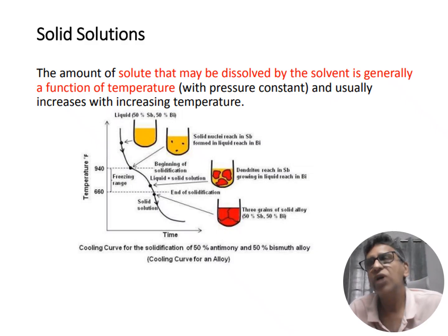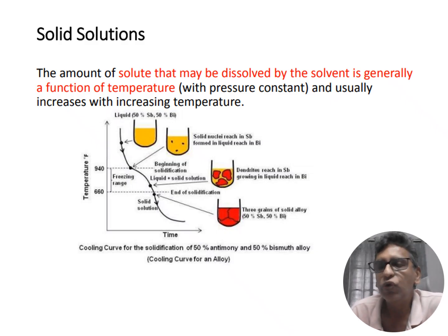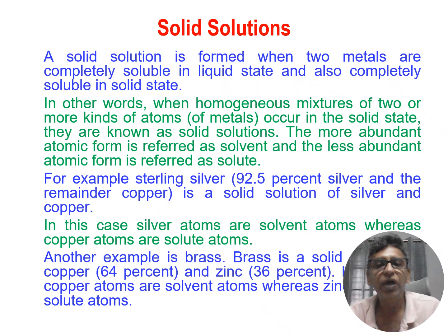So you start with a pouring temperature of 1450 degrees centigrade, and slowly it becomes hard. At nearly 750 to 800 degrees centigrade, it becomes solid, but it is in a very red hot condition. So you cannot take the casting out immediately at that temperature. You keep it for a minimum of 4 hours so that it completely becomes solid and attains room temperature, and then you can take the casting from the mold.